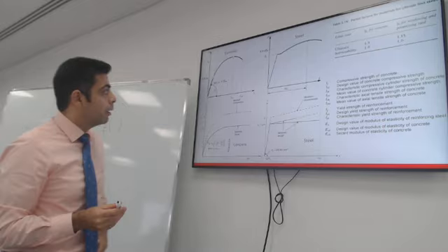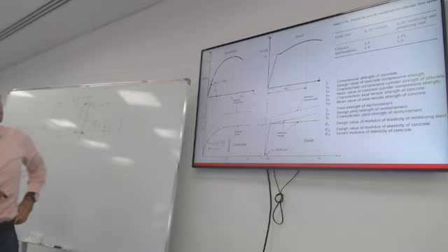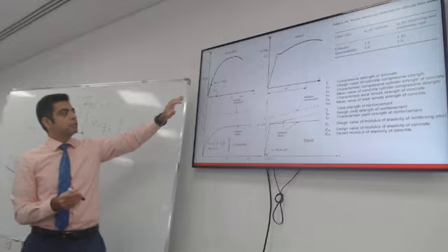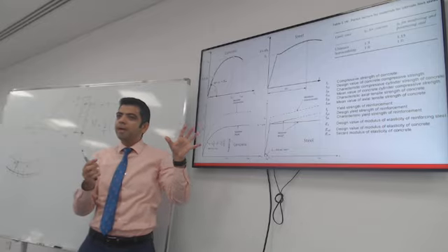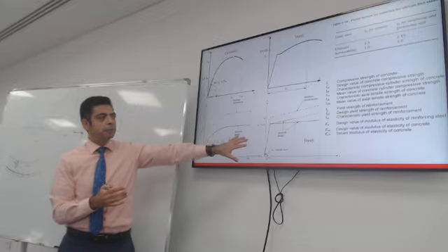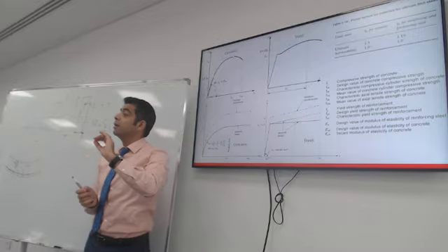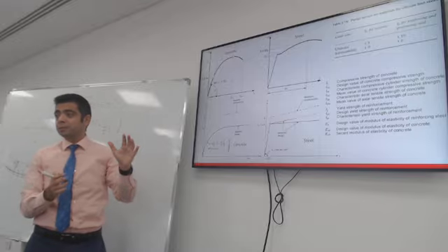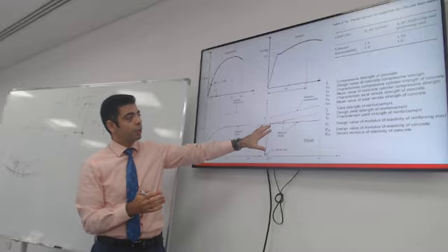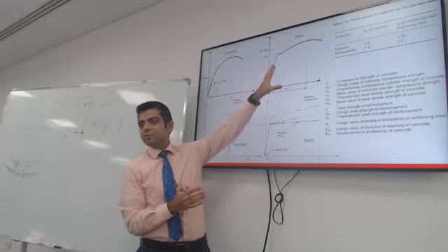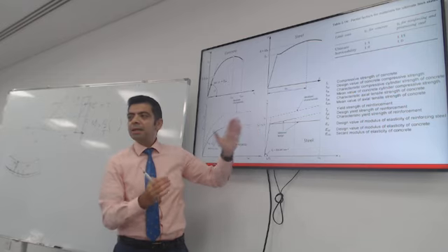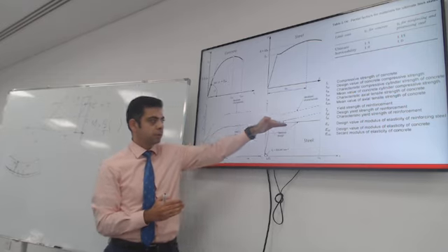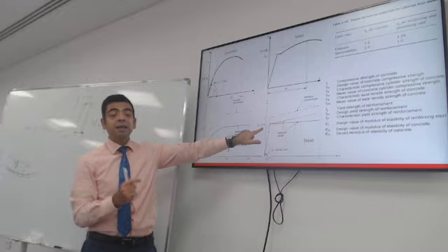So, what is the difference between the top and bottom diagrams? The top diagram is the actual behavior in the lab. The bottom diagram is the idealized curve. So the code will tell us, okay, you don't need to deal with steel that looks like that. Let's make it easier into a linear part and then a horizontal part. And let's take a factor of safety.